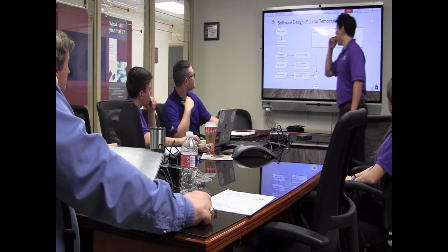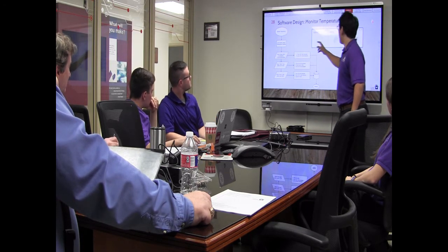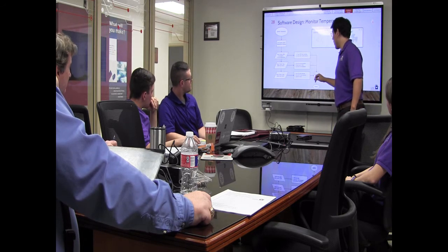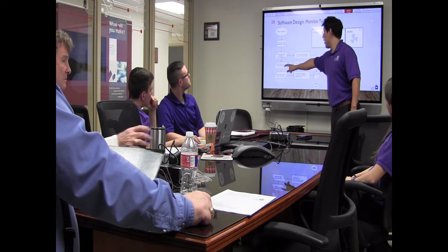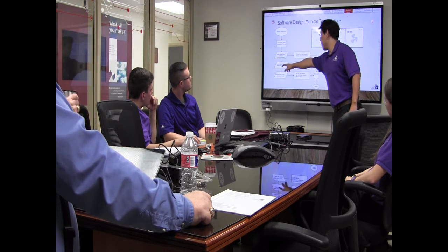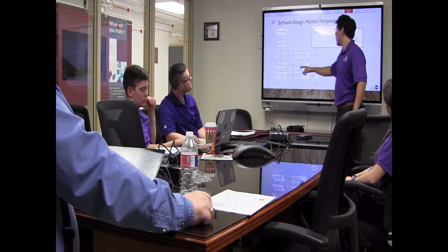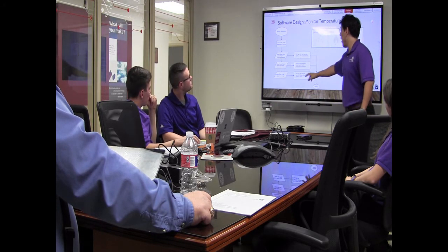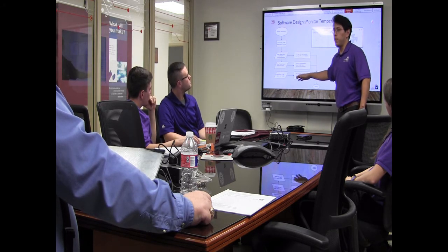So here, if we're within 2 degrees, we turn off the hot and cold indicators and we store this data. We don't send it yet, and I'm going to explain this in the next slide. And then simply if we're below 2 degrees, we turn on the cold indicator, close the air vent, and then turn off the hot indicator. And then the exact opposite is done if we're above 2 degrees of our user set point.